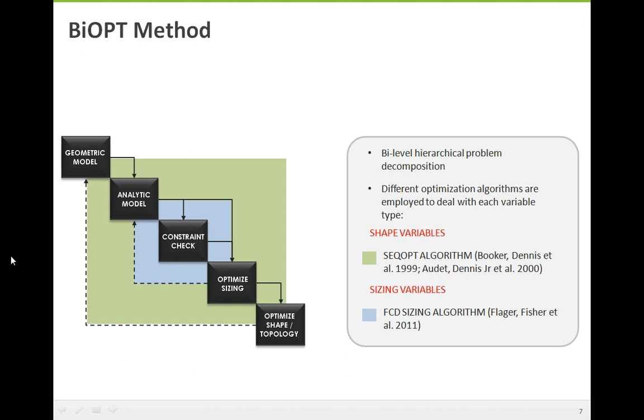That's dictated by the building code in many cases. The client or the design team may have additional constraints that they're placing on it. For example, this roof had a limit on the amount of deflection that it could have in the middle of the arch to make sure that it wasn't perceptible to the crowd.